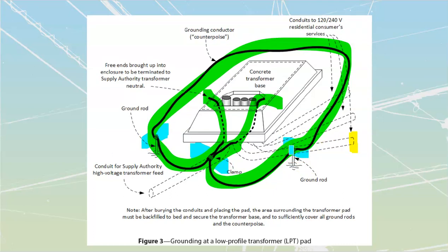Be careful when you're driving these ground rods in that you don't drive them through your conduits. Know that you're going to have two front corner ground rods, so just make sure when you are running those conduits out that you don't have anything at the front corner. Otherwise you've got to dig it up and repair it. It wouldn't be live yet at that point, but it would just be annoying.